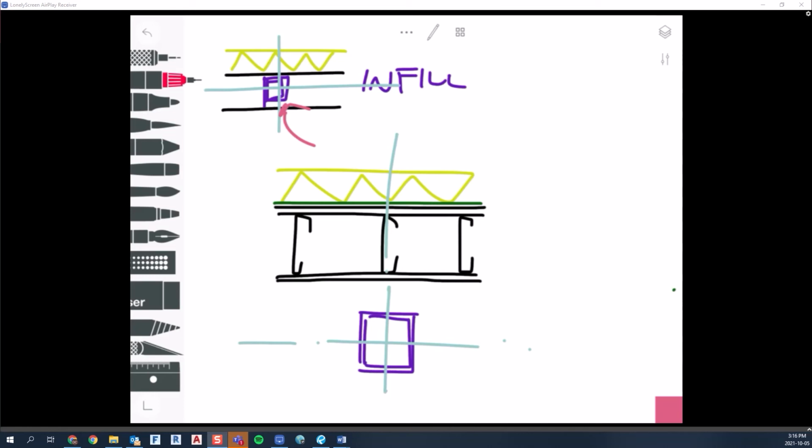And when you're early on designing a floor plan, you might not even have an engineer yet. So taking this bypass approach is a little bit safer, because this column right here can change size quite a bit and you won't have a problem, generally speaking, for the most part.